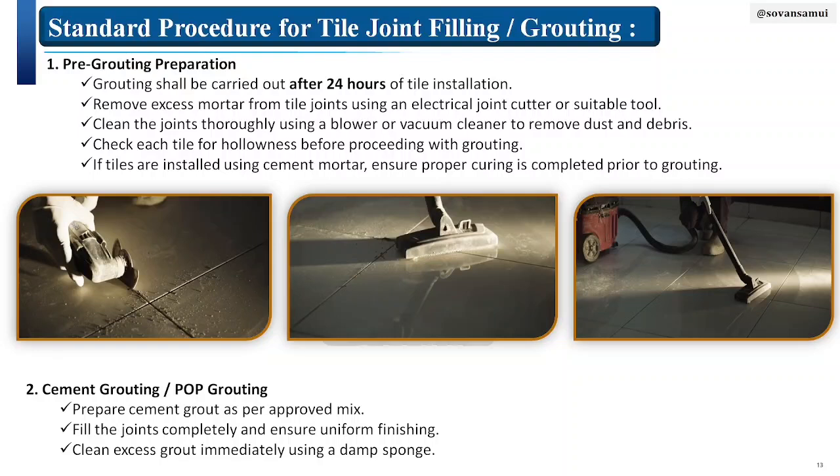Okay, so the first point is the pre-grouting procedure. In pre-grouting, always ensure the grouting is carried out at least 24 hours after the tile work is completed. If tiles are installed using cement mortar, then curing should always be done before grouting, and check each tile for hollowness before proceeding with grouting. If there is any hollowness, you should rectify those tiles, and after that you can go for grouting.